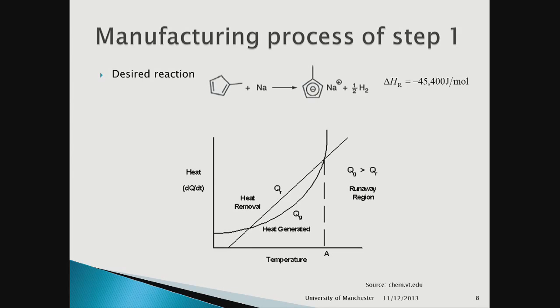10, not so bad, manageable. Anything a bit more than that, when we get to 25, we're starting to worry. By the time we're at 50, we've got to take precautions if it's exothermic, and we've got to know it's not in this runaway situation. So fortunately for me, I've got the temperature, and I've got X, the conversion, which is also the thing that we concern ourselves with. But it's the rate of change of heat. So he's in a runaway, the heat is generated, and we've suddenly run away.